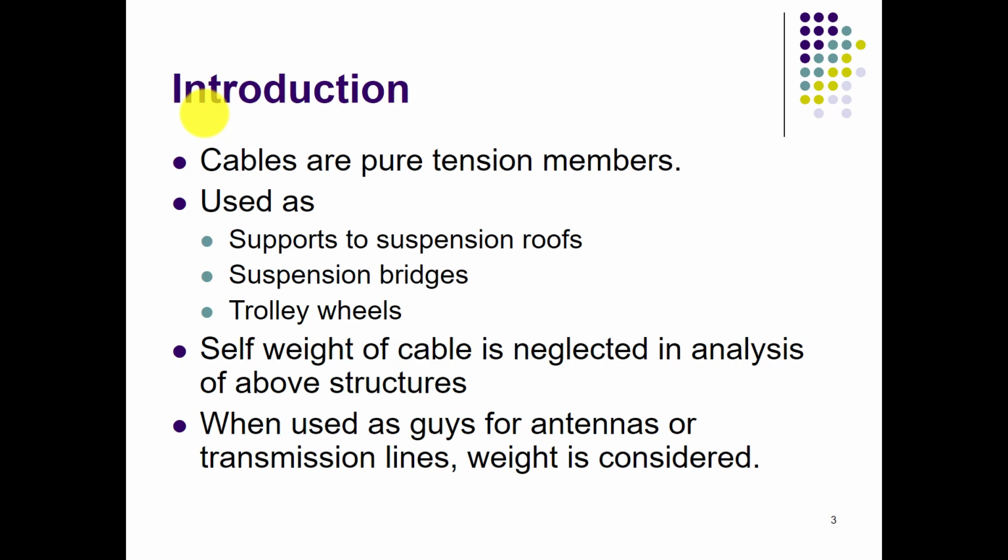These cables can also be used for the transmission lines that I also have mentioned. For the design of a transmission line, their weight must be considered, because the transmission lines have a very long span, and the weight basically governs the design of the transmission towers. So it's important to take the weight of transmission lines into account while designing the towers.